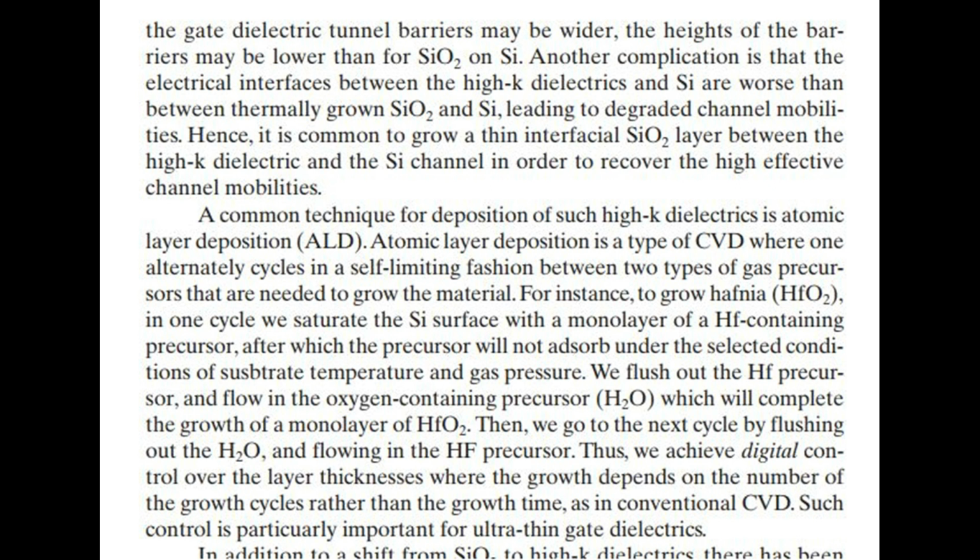Another complication is that the electrical interfaces between the high-K dielectrics and silicon are worse than between thermally grown silicon dioxide and silicon, leading to degraded channel mobilities. Hence, it is common to grow a thin interfacial silicon dioxide layer between the high-K dielectric and the silicon channel in order to recover the high effective channel mobilities. A common technique for deposition of such high-K dielectrics is atomic layer deposition, ALD.